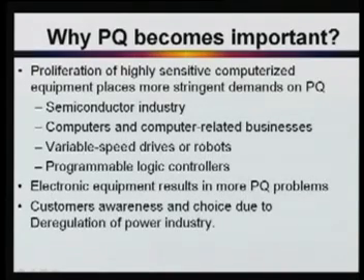Now, the effect of a voltage dip is mal-operation of power-down sensing circuitry in computers and controls. The variable speed drive and the computer trip out. Sometimes your variable speed drive controller may not work properly during a voltage dip, because it senses the voltage, and that voltage is used for the firing circuit.